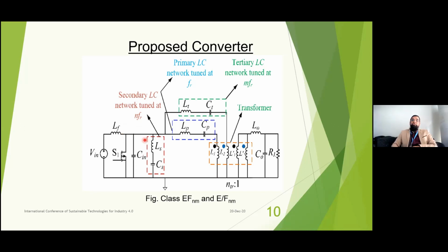So we are delivering 100 kilohertz power to the secondary through the primary resonant tank. Now this is the second harmonic, so this is the 200 kilohertz switch resonant frequency. The 200 kilohertz resonant frequency is being bypassed through this resonant tank. This helps to reduce the peak switch voltage, but because you are now bypassing the second harmonic, you are losing a lot of power.